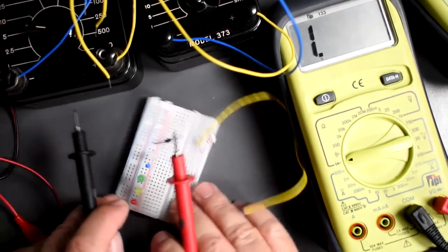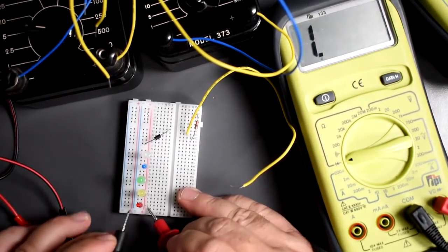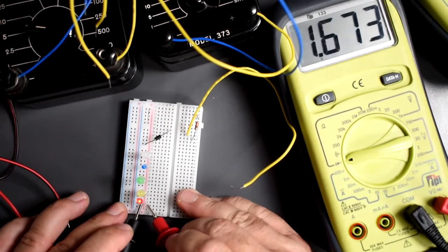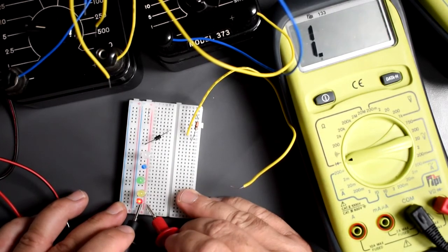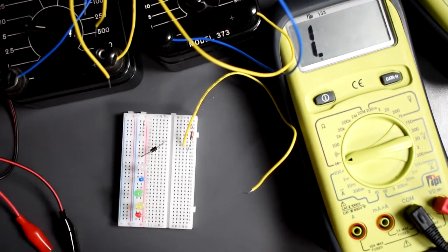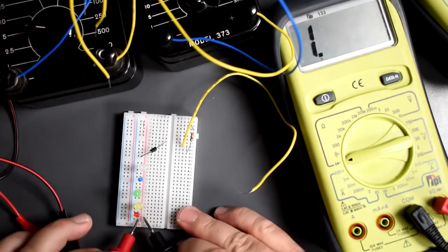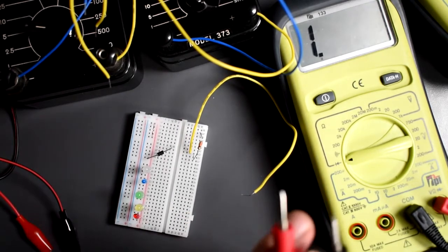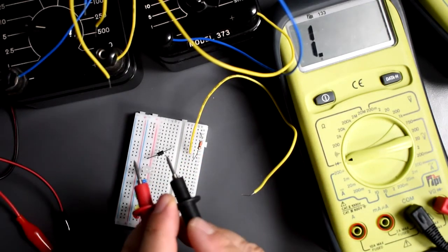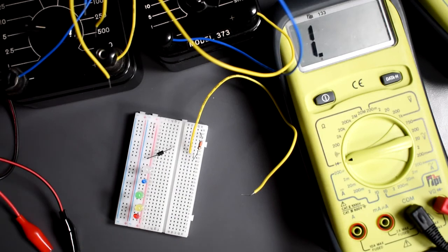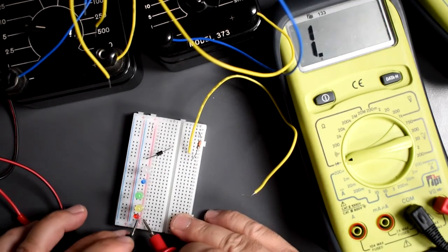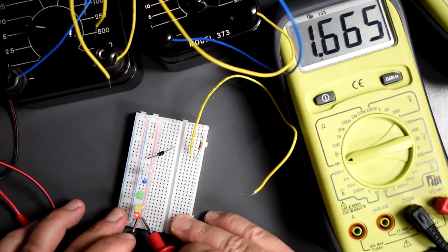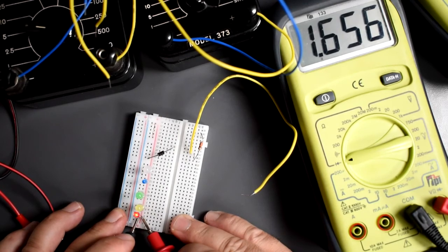Let's take a look at other ones. The red LED, and you can tell that the forward bias is there because the LED is going to light up a little bit, because the continuity resistance and diode tester introduces a little bit of voltage across the probes. Okay. So let's just take a look at what is the forward bias voltage on this. This one shows that this diode should have 1.6 forward bias voltage.